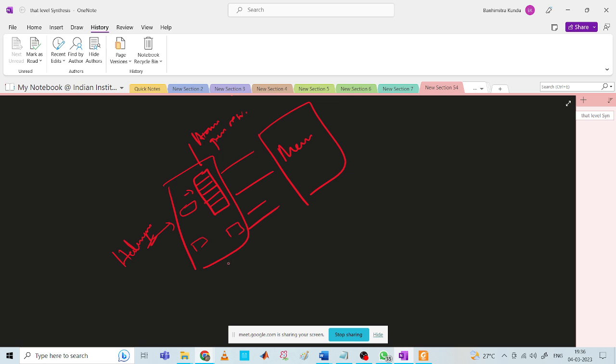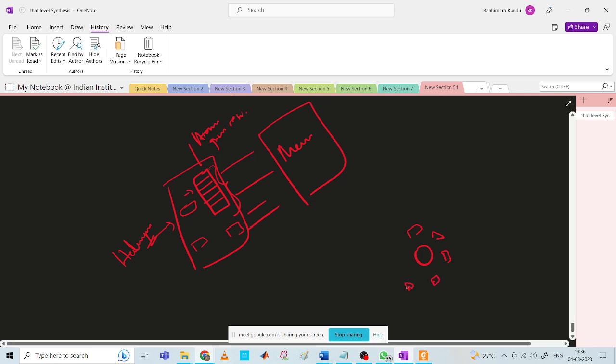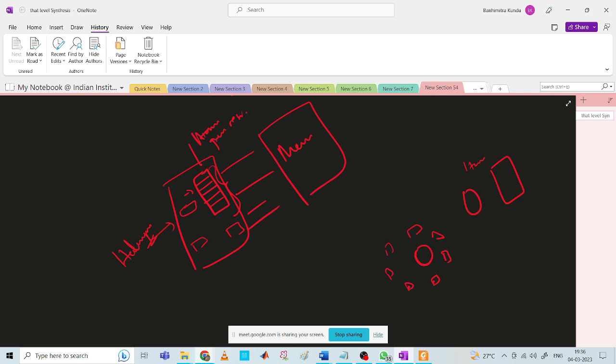Now, what is the advantage of heterogeneous registers? The advantage is you do not need to have all the registers packed at one place, because that will simply use up your space. So you can scatter your registers in such a way, let's say this is your processor core. If you scatter registers in this way, this is a heterogeneous arrangement. But if this is the core and you are making your register file in this way, this is called homogeneous. So this can sometimes lead to space issues.